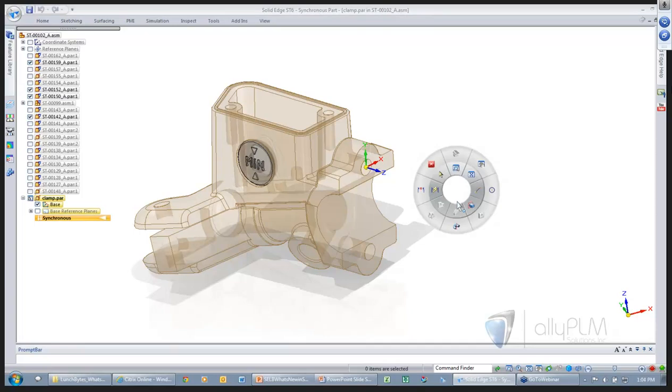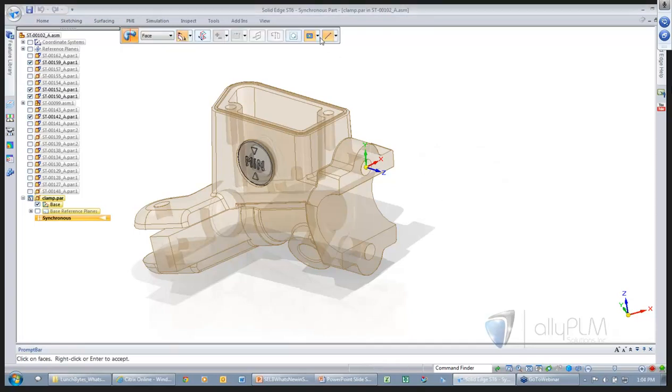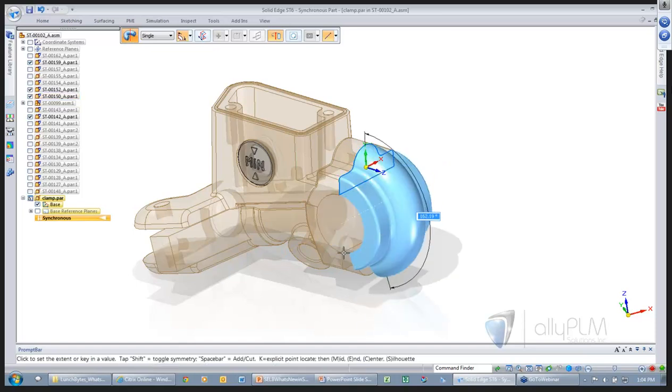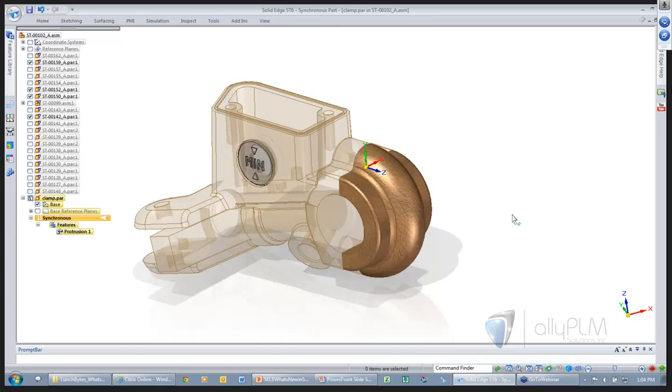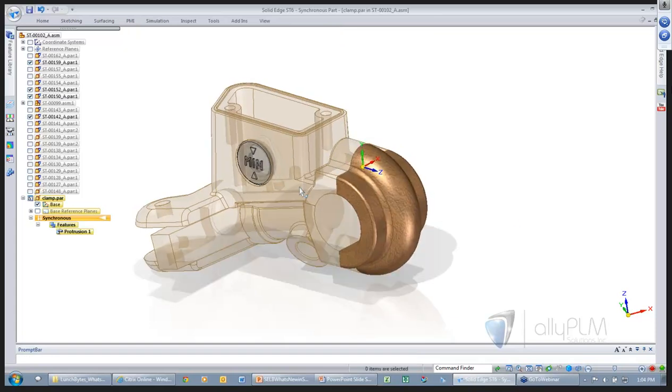Now I really want to revolve this. So same idea, I'm going to go to Revolve. I want to exclude internal loops because I do not want to revolve that hole. So I'm going to revolve it about this center line and sweep that around to a point 180 degrees. There's my revolve shape. Now, there were those holes in there.